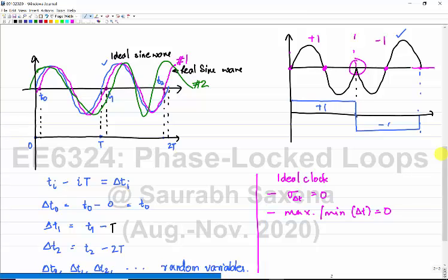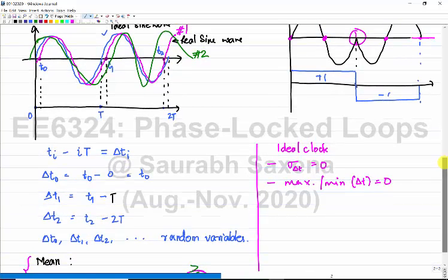Okay, so this is the kind of metric which we are going to use. Now, in order to judge how good my clock is, what did I use? Did I use voltage values like any peak values as shown here, or actual amplitude? Or did we look only at the zero crossing? The answer is that we looked only at the zero crossings of the clock. The information we would like to have is a perfect zero crossing without any deviation. Amplitude can vary, it may be fine.